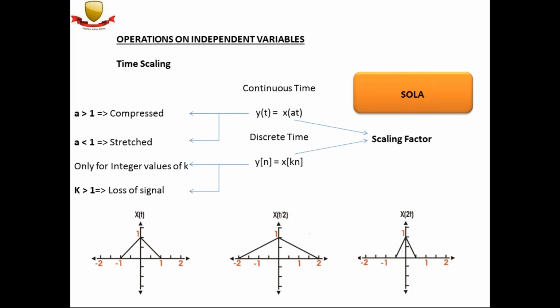It works by cutting the sound data into short sequences between tens to hundreds of milliseconds each, and then joining these sequences back together with a suitable amount of sound data, either skipped or partially repeated in between these segments or sequences to achieve a shorter or longer playback time than the original.